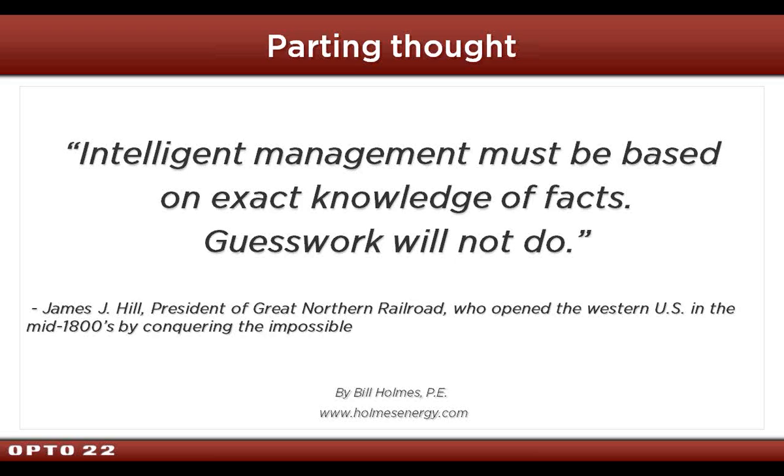Yeah, Bill, I could maybe add a little anecdotal information for Damon. With BAS systems that are in place, BACnet is very common. Modbus is fairly common. And we've seen some power monitoring devices that do harmonic analysis, et cetera, that you could tap into, and many of those speak Modbus. So I would say Modbus and BACnet are things that we've seen out there. Hopefully that helps, Damon.